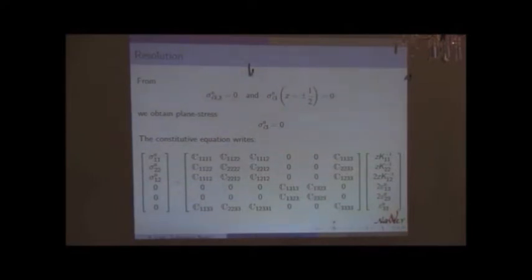Of the moment tensor. So just to see if there is any compatibility, if you have zero shear stress, to see if you have exactly the Kirchhoff. So what will come out here is that the shear stress at this order vanishes. Of course, the whole point of this asymptotic expansion is to go to higher order and capture those shear effects. So at this order, the order of Kirchhoff-Love theory, we are in plane stress.